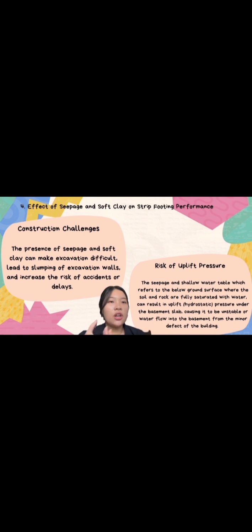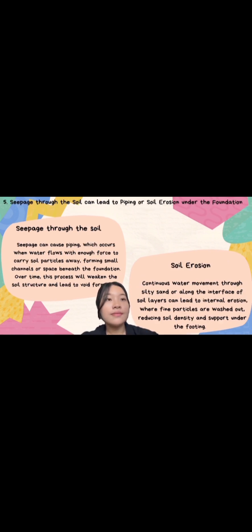The seepage and shallow water table, which refers to the level below the ground surface of the building where all of the soil and rock is fully saturated with water, can result in uplift, which is hydrostatic pressure under the basement slab, and it will cause it to be unstable, or water to flow into the basement from a minor defect of the building.